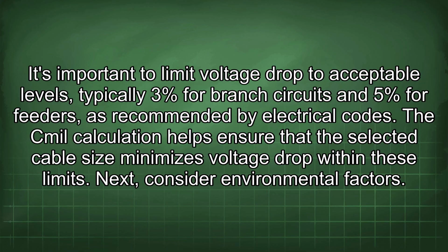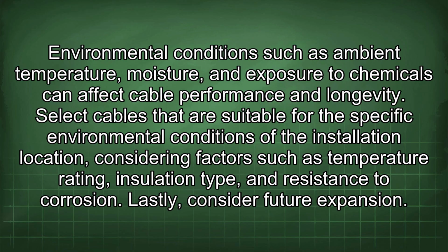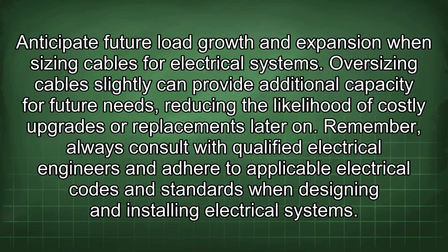Next, consider environmental factors. Environmental conditions such as ambient temperature, moisture, and exposure to chemicals can affect cable performance and longevity. Select cables that are suitable for the specific environmental conditions of the installation location, considering factors such as temperature rating, insulation type, and resistance to corrosion. Lastly, consider future expansion. Anticipate future load growth and expansion when sizing cables for electrical systems. Oversizing cables slightly can provide additional capacity for future needs, reducing the likelihood of costly upgrades or replacements later on.